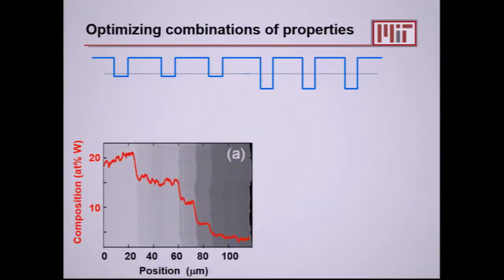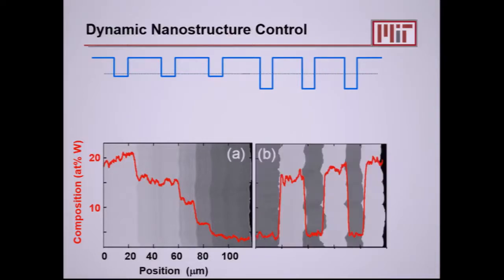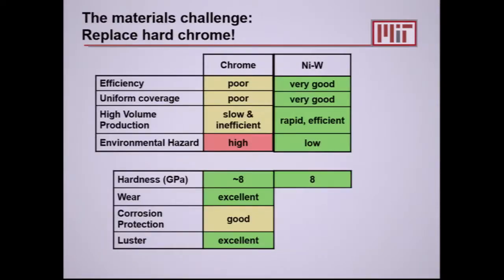So I can make materials that have all kinds of different grain sizes through the thickness. I can do functional grading, I can do Neapolitan structures, layered structures, any coating you want. Grain size is no longer a variable, it's now a state variable, right? It's a position-dependent variable. And that turns out to be remarkably useful, and I'll talk more about this tomorrow, but when it comes to wear, it's not just about being hard, it's about distributing damage. And so if you can control many different layers, you can control the way damage evolves.